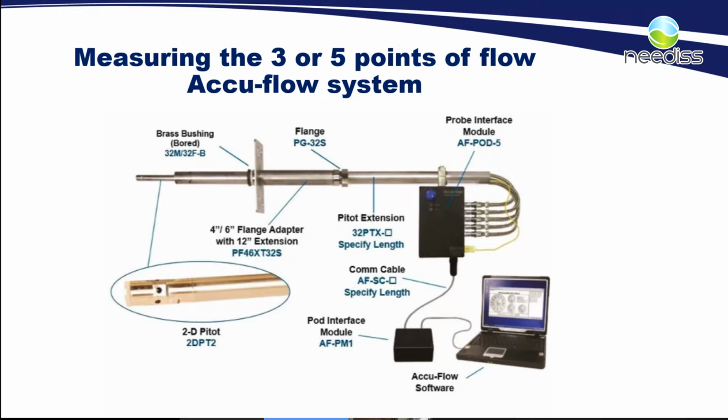So instead of having to traverse maybe all 12 or 16 points across the stack with one single probe, if you wanted, we could have 4 different probes attached to one single laptop and sample 4 points simultaneously, and then traverse all of those pitots outwards in the stack at the same time, and record the next points and the next points.